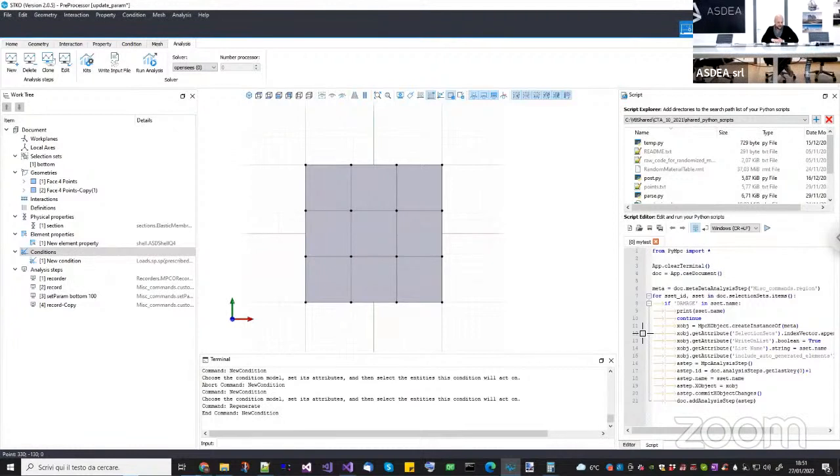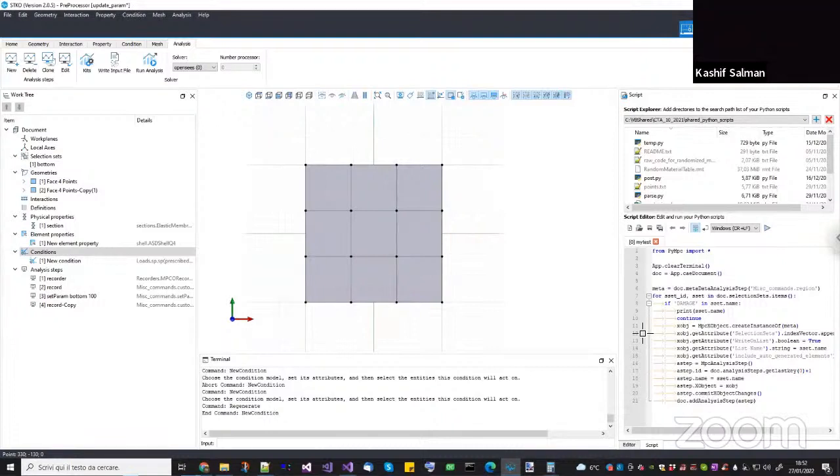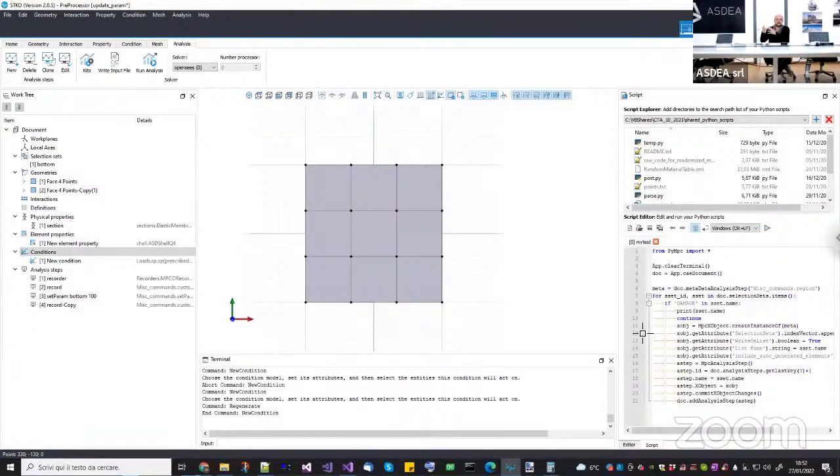Yes, in the way you want to model it, it can be done, because if I understood correctly, you want to model the non-structural component physically inside your structural model, and you want to create an interaction between them, which is not a simple equal degree of freedom. It's something like a contact, a frictional contact, or nonlinear springs, right? That's right. Of course, you can do it. You take your non-structural components, you put them inside your model, and you need some way to decide what the interaction is. It can be a simple kinematic constraint up to very complex contact conditions.